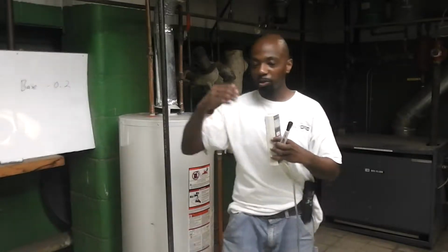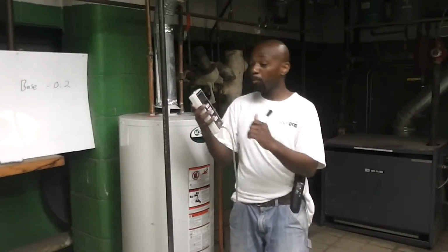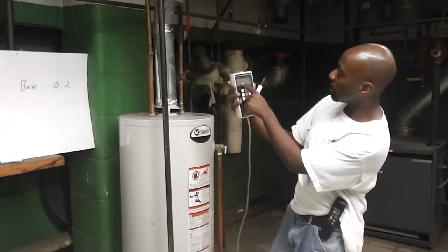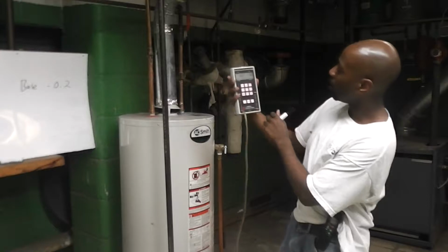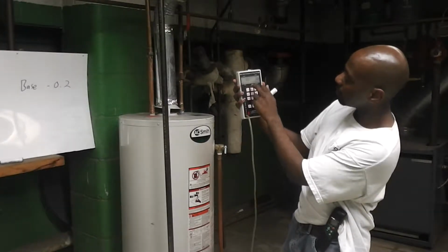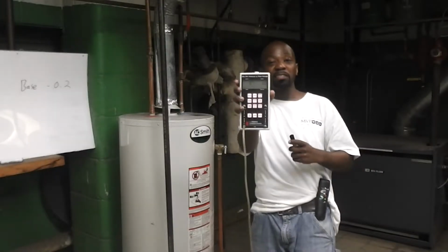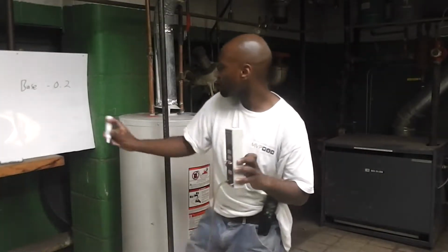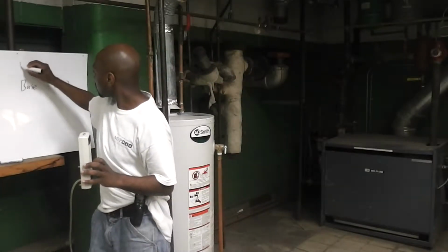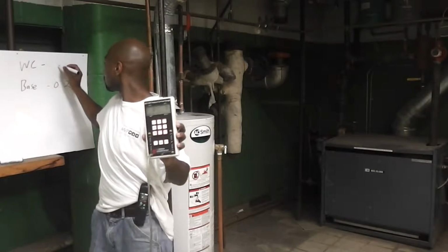So far, I've turned on anything that can make this place more negative. I want to see what that difference is. My new pressure differential looks like it's at 0.9 or 0.7. It's going to fluctuate for a bit. Looks like 0.8 or 0.5. It looks like an average of 0.7, so I'm going to put that as my depressurization. Worst case was 0.7.